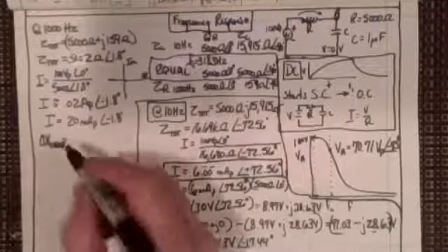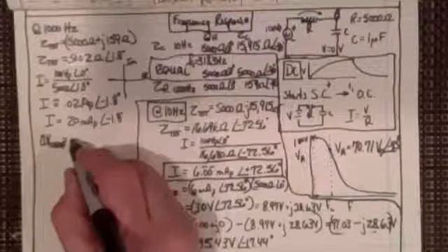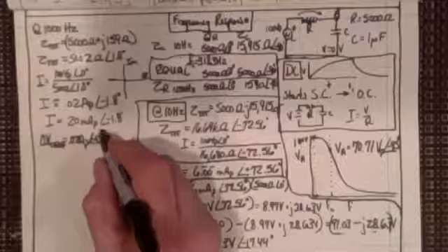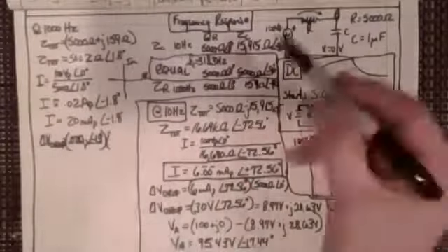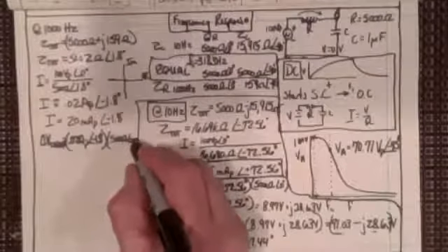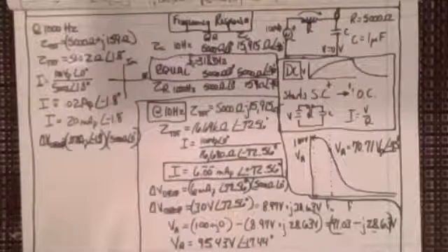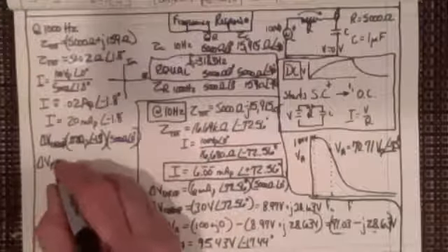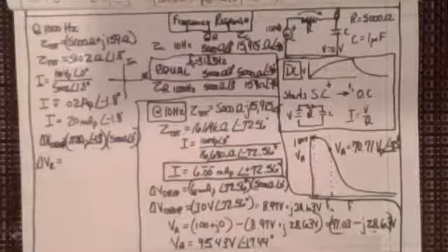So the voltage drop that we're going to get is just going to be, I'll just write it this way, 0.02 amps peak at minus 1.8 degrees, which I have right above it, so you can see what I'm actually writing there, times R, and R is going to be 5,000 ohms at 0 degrees, right? So my voltage drop across the resistor, I'll just put delta V sub R there, is going to be 5,000 times 0.02.